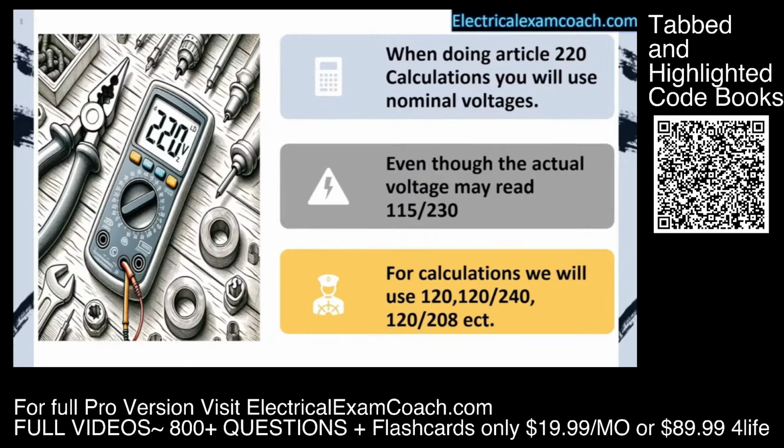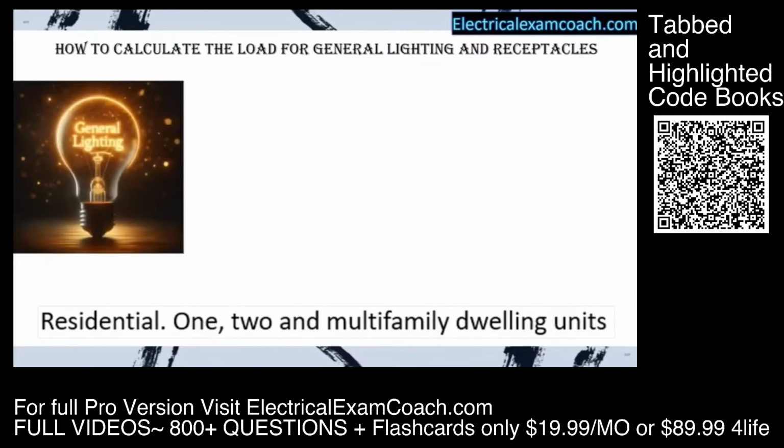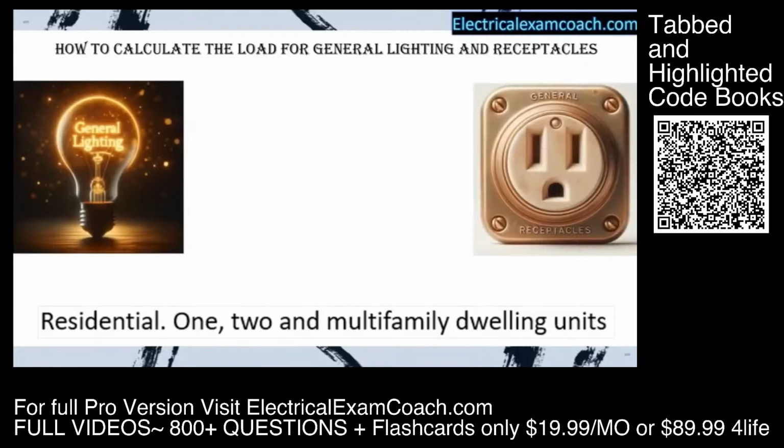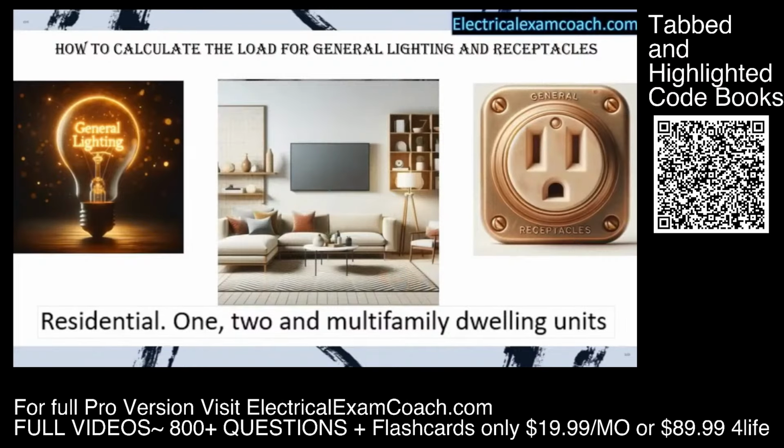The first thing that we're going to learn about for our whole home load calculation is how to calculate the general lighting and receptacle loads. This is going to cover all of our general lighting and general receptacles in places like bedrooms, living rooms, hallways, everywhere that's considered a general area. We've grouped all of them together and come up with a very easy way to do it. Now, what I'm getting ready to teach you only applies to residential 1, 2, and multifamily dwelling units.